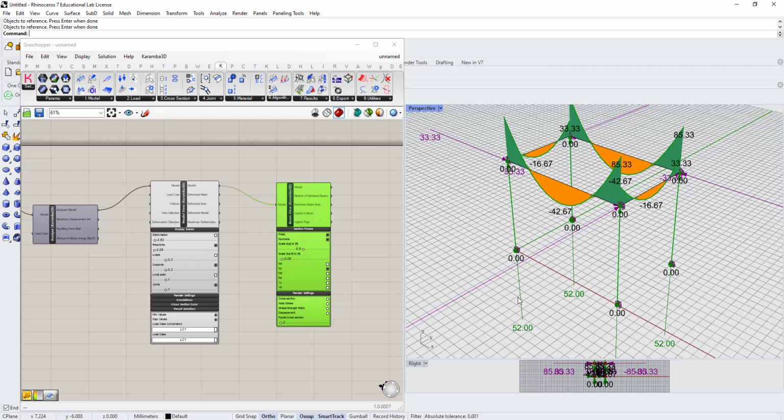And you know that stress equals P over A, force over the cross-sectional area. And again, you can look into the allowable stress of columns. If you look for steel, it's again 22 KSI, and the force here is 52 kilopounds. Make sure that you're doing the calculation right, and find the required cross-sectional area.